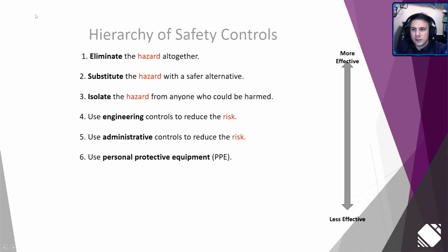So you have to analyze it and look at the safest installation, and then isolate that hazard. A great example is 230,000 volts. You want that high enough above any work plane such that nobody is at risk. In the first lecture, I talked about the example of somebody standing on an elevated platform to operate the controls, and as long as they were lower than a certain height and not putting their arms in the air, they were safe and isolated from the power.